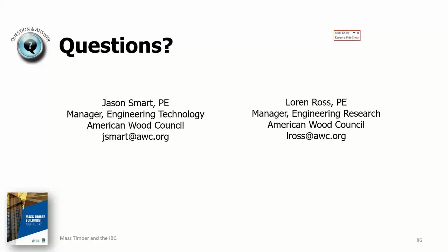I believe the US CLT Handbook has a chapter on it. That's right, the CLT Handbook is one of those. But that is a good point, that adding that mass, while it improves sound transmission loss, could also bring you down into the frequency range that's considered annoying for vibrations.